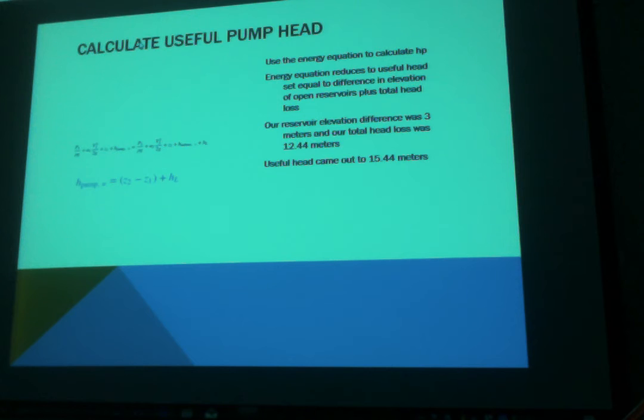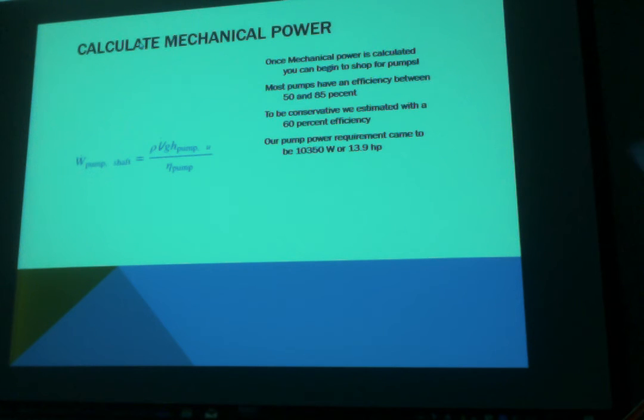After we calculated useful pump head, we could then calculate the mechanical power required by our pump. Now, most pumps have an efficiency between 50 and 85%. To be conservative, we estimated with a 60% efficiency, which brought our pump power requirement to 10,350 watts or 13.9 horsepower. Once you calculate the mechanical power for your pump, you can begin to shop for pumps.